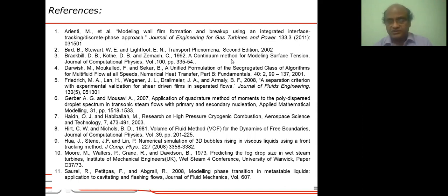That is, suppose we have a stream of air which is moving at 1 meter per second, and into that, if we put some particles which are at zero velocity, then this particle will gather momentum. Momentum will be transferred from the air to the particle. So this is added as a surface force or source term to the particle momentum equation. At the same time, the same amount of momentum should be subtracted from the air. Only then will we get the correct flow field. So that goes as a negative source term for the Navier-Stokes equation for the carrier fluid. Now, then there could be pressure forces.